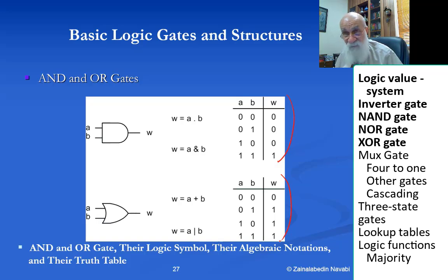If you want to do a CMOS circuit, with the PMOS and the NMOS, the only way you can do an ANDing is to have a NAND gate and then have an inverter after it. So for example, if you want to do an AND function, this is what it becomes.